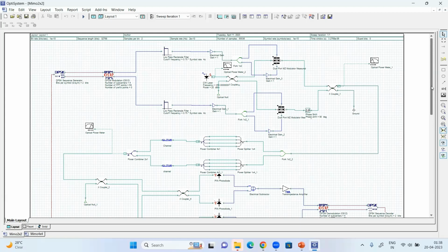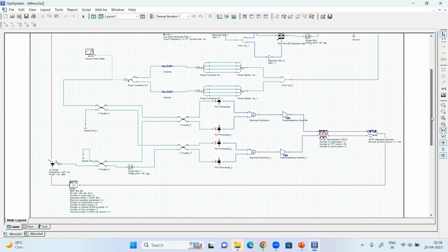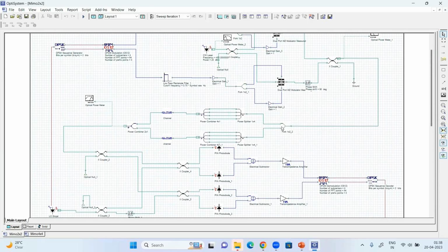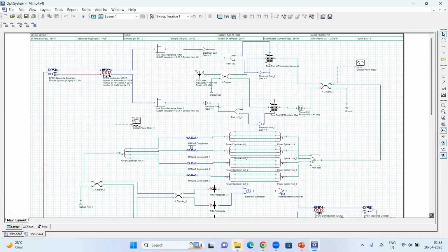Unlike the SISO schematic, here the transmitter sends the data directly to a fork which splits the signal in two. The resulting signals are then transmitted to a different MATLAB component, including the underwater channel with the Alamouti coding technique. Here, the underwater channel consists of all the losses which happen in a real-time system, and to enhance the same deteriorated signal, the technique is used. The output signal is then sent to the receiver component, and it follows the same steps as the SISO schematic.